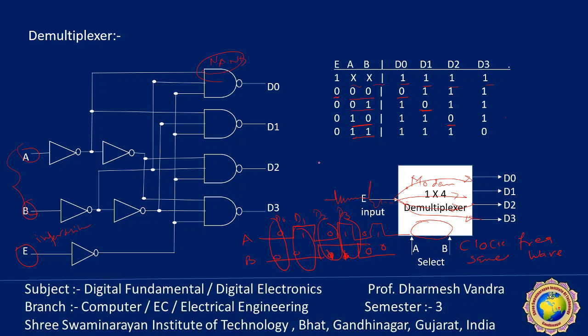So if my input frequency is 100 megahertz, it is equivalent to 25 megahertz divided into each connection line. So in this way, we can demultiplex our input signal, the internet line, into four different equal frequencies, but using the clock, or you can say a sequence generator. So in this way, a practical approach to using the demultiplexer in real life is possible.